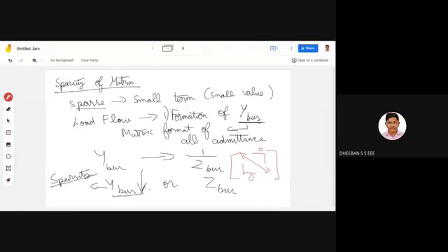Also, this sparsity rises. Why it rises means at the diagonal elements. At the diagonal elements here, you can see that more buses will be connected. If you are considering a single bus and it is connected with n number of buses, in most cases the diagonal element represents the interconnection between all the other buses, and hence this diagonal element value will be higher in value.